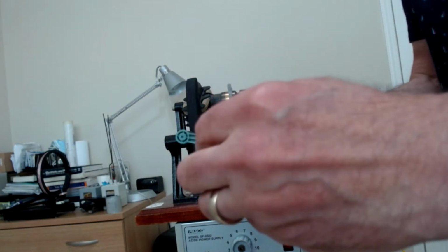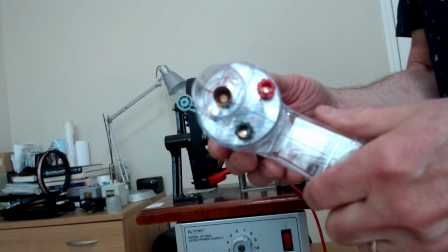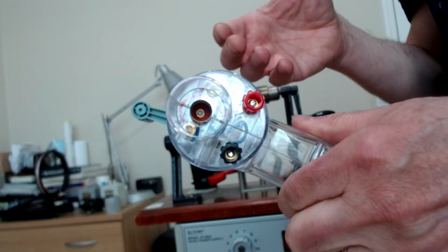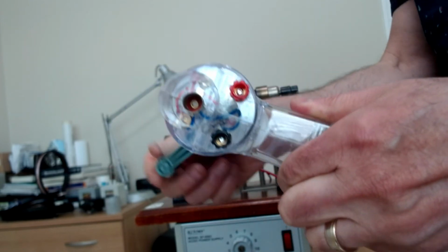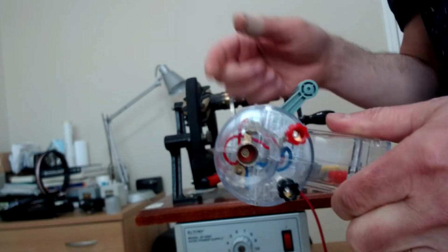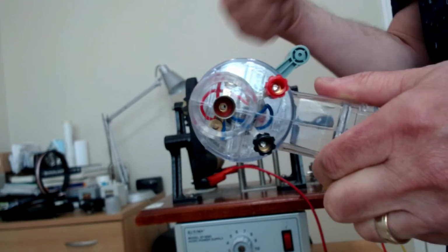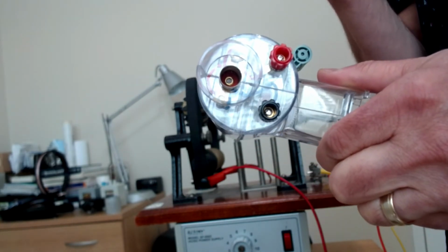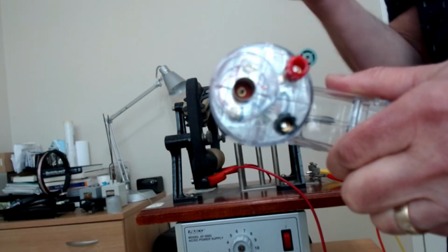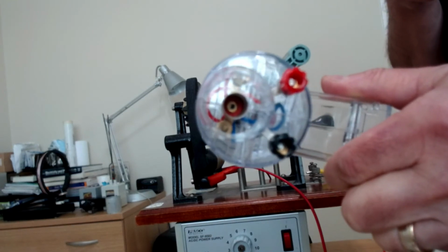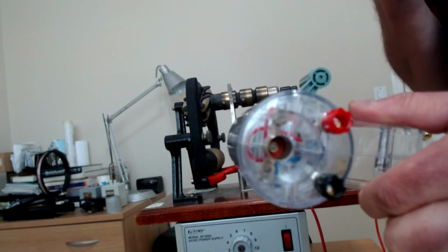If I take this bulb out, I have no current in my circuit, this open circuit. And so when I rotate this, since there's no current, I can keep this going at a constant speed, no problem. Obviously, I have to overcome friction to keep it going at a constant speed. But once I've done that, it's going to go at a constant speed. It's going to be easy to spin. But once I put in a bulb, the bulb is using energy. It's taking energy from me. I have to put in more energy to make this turn at a constant speed. Does that make sense? And so that torque that's produced is called a counter torque.